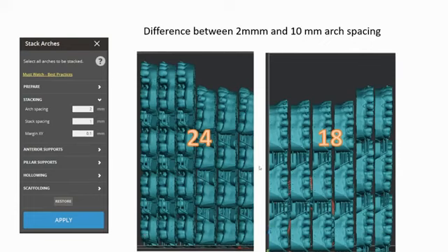If you open that function, there are a lot of preferences and parameters that you can change, and one of those is the arch spacing. So what you can see on your left side is the default setting. There is only, I think, 1 millimeter in between the arches, the vertical stacking. If you change that, you will see on the right side that this influences how far these models are away from each other vertically, but also will reduce the number of models that you can put into the stack. So you can play a little bit with this setting, but I think we optimized this quite well.